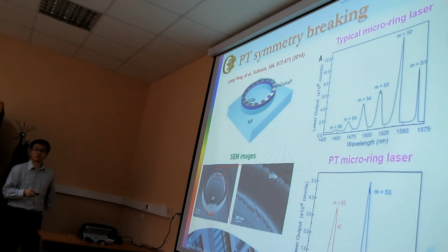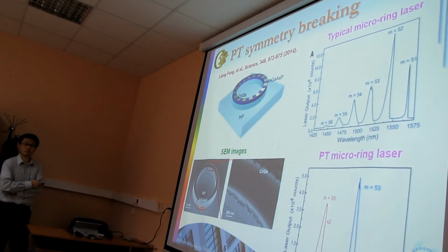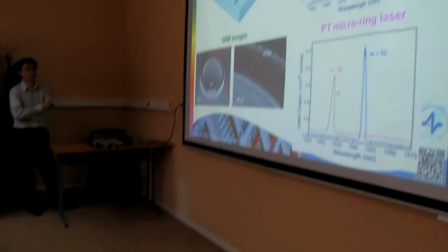Only one mode. That will be very helpful and very promising for making VCSELs with a larger size that operate in single mode at high power. Typically VCSELs only operate at very small powers, so the applications are limited. The main application fields for high power lasers are dominated by edge-emitting lasers. But I think VCSELs can have better geometries in terms of the heat sink and the fabrication process because it's vertical.